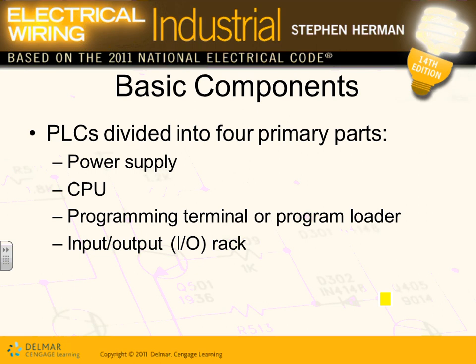The major component of PLCs, Adam, these are the four major components. The first one is the power. So power supply. So you get the 120 power supply or 277 power supply to these PLCs, and you convert it to 5 volts or 24 volts so you can power the electronics of the PLCs and use these voltages as control voltages. That's the first one.